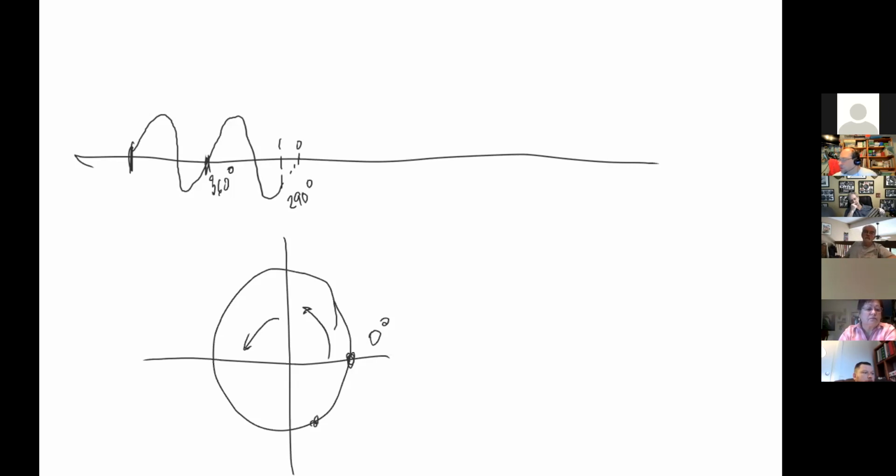We've gone through that much of the circle. When we hit a phase shift, we would change it by 180 degrees. So we would have an instantaneous change up to wherever the graph shows that we're up here, and we would continue going right here. So that change right there is a phase shift, and that would basically represent a change of data, and that's known as phase shift keying. It changes the phase of the signal.